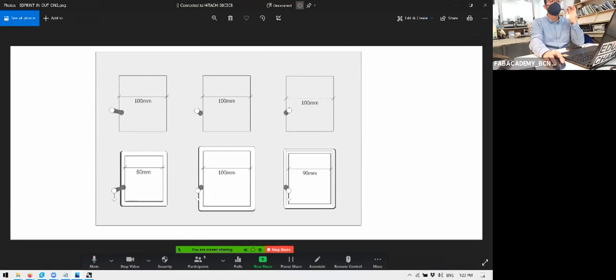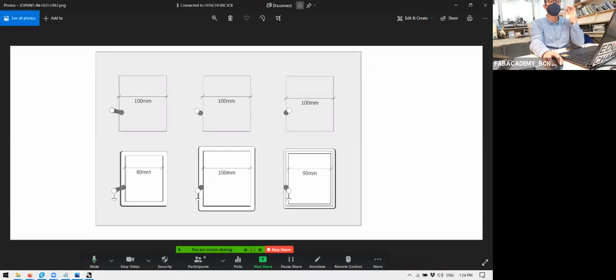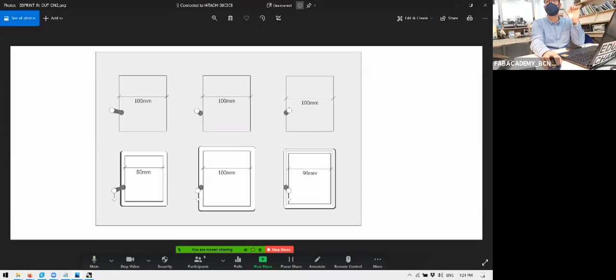If we have this vector, we can cut with the end mill on the interior of the vector. We can cut on the exterior of the vector, or we can cut on the vector with the end mill aligned, end mill touching outside, end mill touching inside. This will give different results.